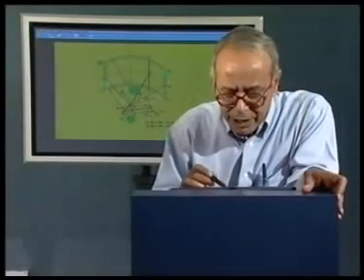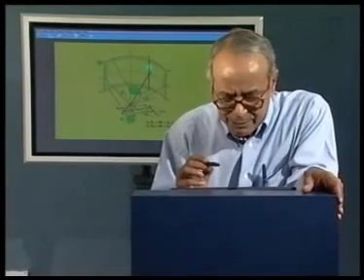That is, CE CF is the same as E2F2 and E1F1. So with center as CE and radius as O4C, which is the same as CE E1, I draw this circular arc. Similarly, with center as CF, I draw this circular arc, and these are the two extreme positions, and the wiping field is what has been shown by these hatched lines. So, we have obtained the field of wiping for this particular mechanism.